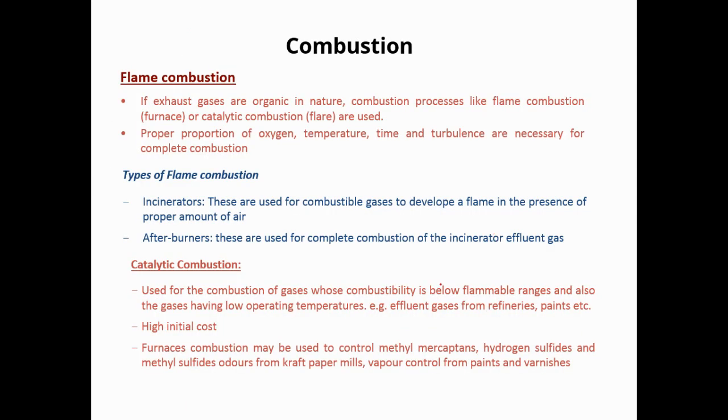Okay. So lastly, the gaseous pollutant removal from the gas-laden stream can be called the combustion process. Combustion means if incomplete combustion takes place in the plants or in the industry, then at the upper part, while discharging the gaseous pollutant, we have to just burn it out, because if complete combustion takes place then only carbon dioxide is released, and carbon dioxide is not a pollutant gas.